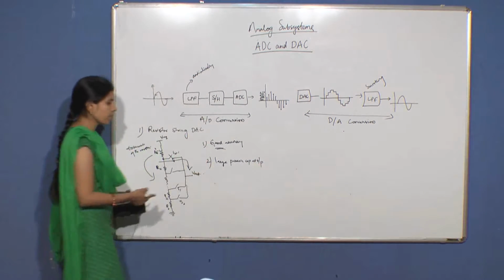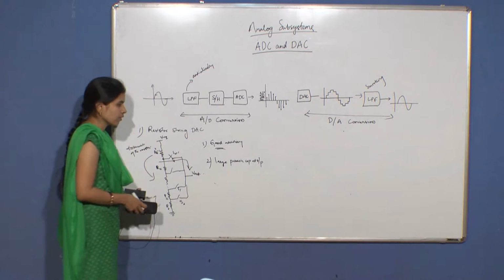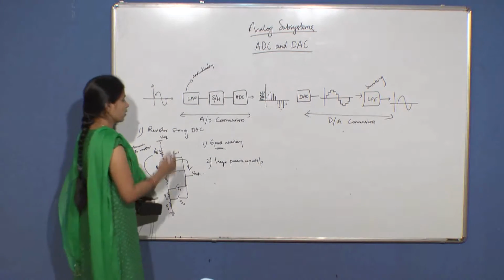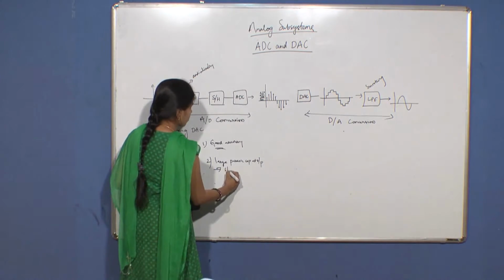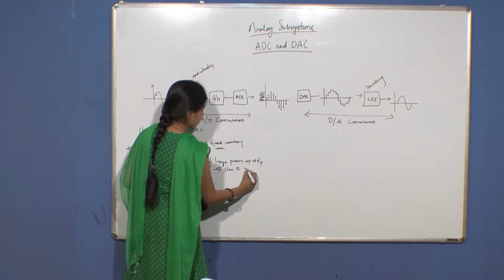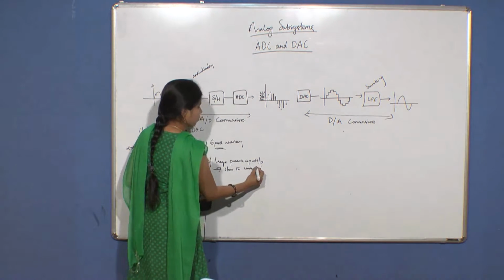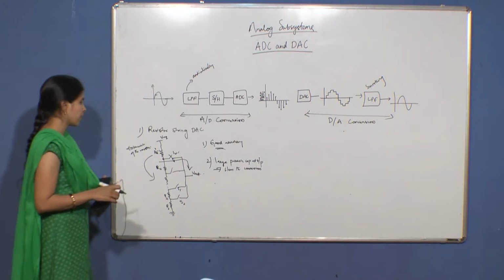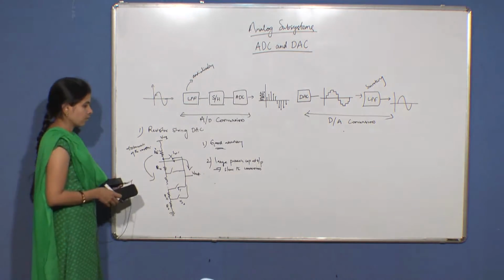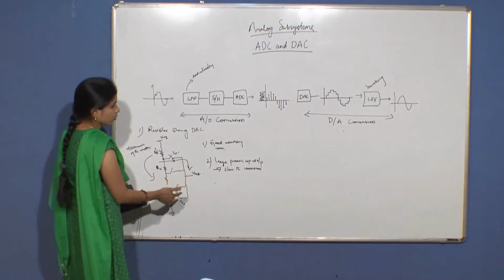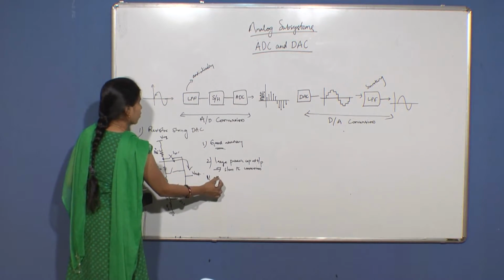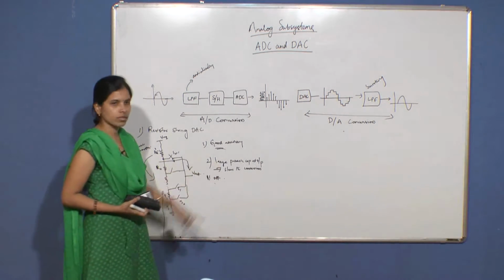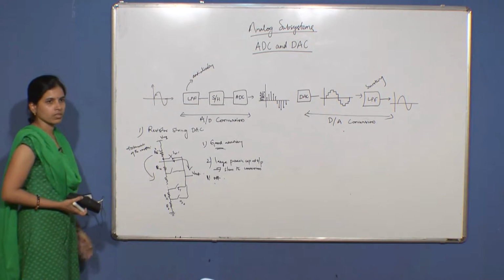Because of this large parasitic cap, the conversion is delayed, so it slows the conversion. Another alternative for this problem is to include binary switches, which allow the output to connect to n off and n on switches. So you can eliminate the problem of large parasitic cap by introducing the binary switches.